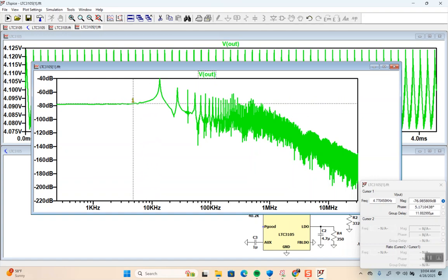So if I go to 1.3, right, and it goes down by 20 dB per decade, by the time it gets to here, that extra 40 is now 20, but it's still higher. Well, if I set it here and make it second order, it drops off by 40 dB per decade.